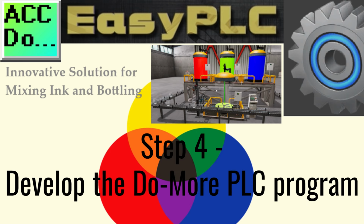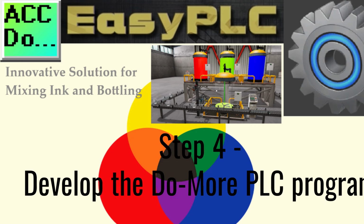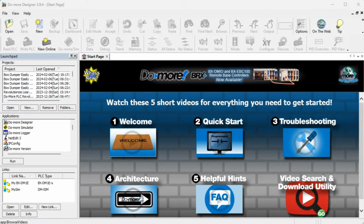Step 4. Develop the Do-More PLC program. Developing the Do-More PLC program is the next step in learning how to program the ink mixer. This step involves taking the logical sequence of operations developed in the previous section and translating it into a program the PLC can execute. To begin, it is important to understand the programming language used by the PLC.